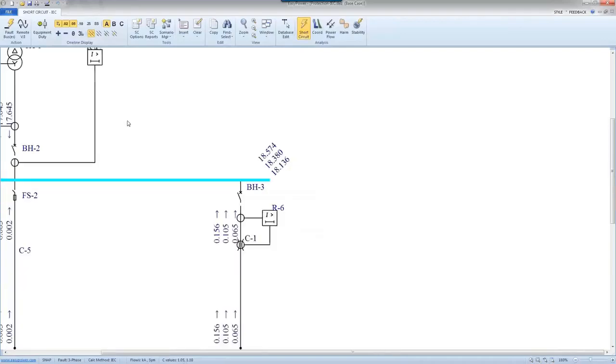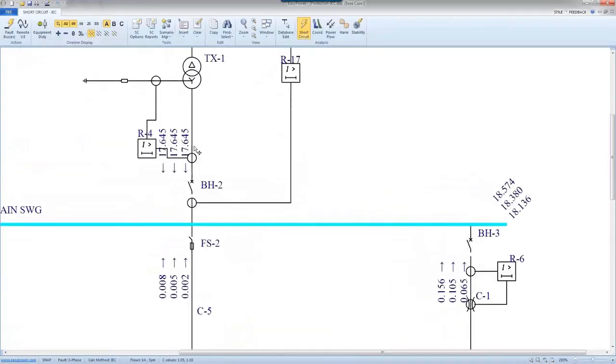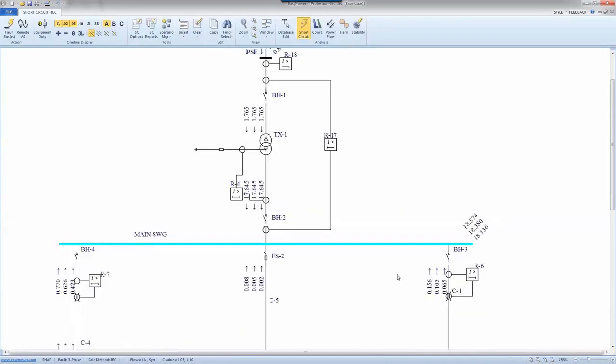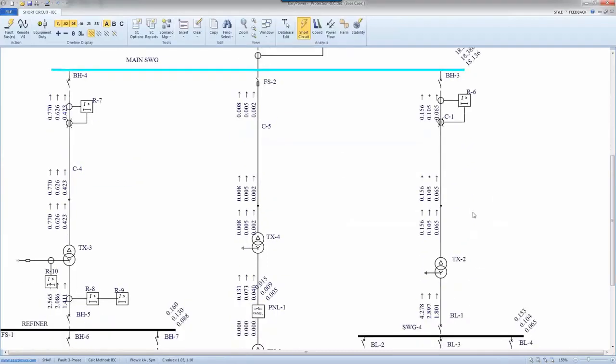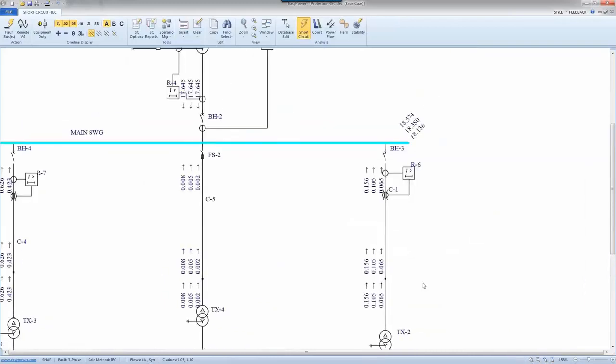And again, you see that I'm very cautious using this terminology. That's not always the case. If you have a stiff source, it doesn't care. It does not decay. It just has the same short circuit value, same contribution over time. However, that's an entirely different story when you look at devices like generators and motors, being a synchronous or induction motor or generator. You would expect decay from them. That always is not the case. There might be exceptions, and we get to those exceptions.